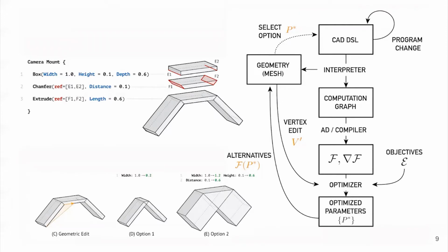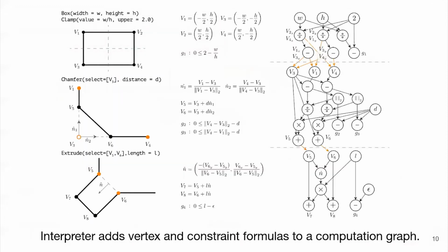So we use optimization of a version of our objectives, which tell us how close a certain set of parameters is to satisfying a given user edit, right? So the edit is specified as a movement of model vertices, and we would like a function that tells us, okay, how close are you and which direction should you go? And so allowing the solver to call these in the inner loop allows us to conduct a fully global nonlinear optimization at relatively interactive rates. And in this optimization, we run several different optimizations with several different heuristics, which generate many possible results for ambiguous edits, which are then returned to the user, and then they can select between them. The user selecting them causes the parameters to be modified, and the process starts again, allowing users to quickly edit, select, and iterate towards their desired goal.